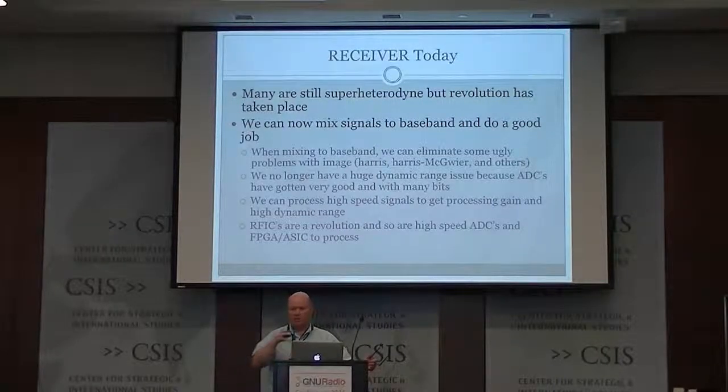The other thing they have is a bunch of oscillators in them, especially because you remember you're going to mix things up and down. The oscillators introduce noise. That's phase noise if it's synthesized. So all of these things are really, really, really bad. They multiply, they mix, they add nonlinearities, noise, and distortion to the incoming signals in these superheterodyne receivers.